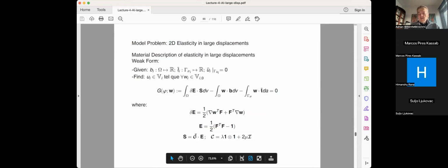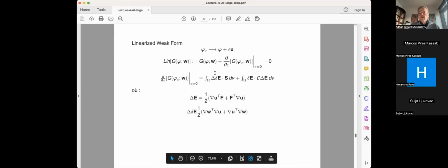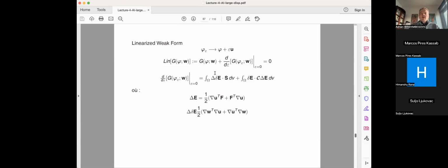You use a Saint Venant-Kirchhoff material, and if you want to go with the isoparametric interpolation, this is one of the rare cases where linearization and discretization can be interchanged, because isoparametric interpolation gives the value of the fields you are trying to compute, either displacement or strain or stress, as just a linear combination of the nodal values. Hence, you can first linearize the problem and then discretize.